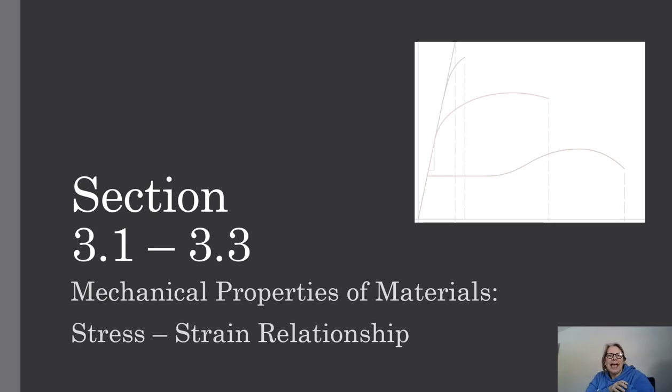Now take a paper clip of the same diameter, made of a different material, and put 10 pounds on it. It has the same stress, force over cross-sectional area, but a different strain. So the relationship between load applied and deformation is a function of the material.